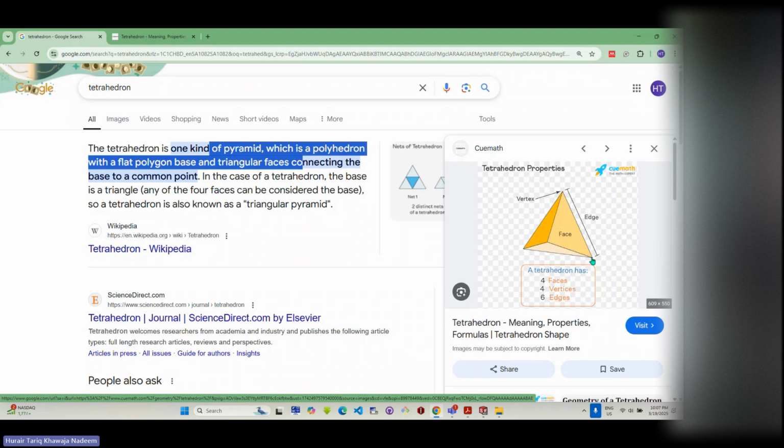Okay, and then you'd solve everything. So the edges or the faces actually have no meaning in terms of calculation. Nodes are very important. So what are nodes? One, two, three, four. So this has got four nodes, and if each node has got 3 degrees of freedom, for example, translation in X, Y, and Z, this means the total element has how many degrees of freedom?